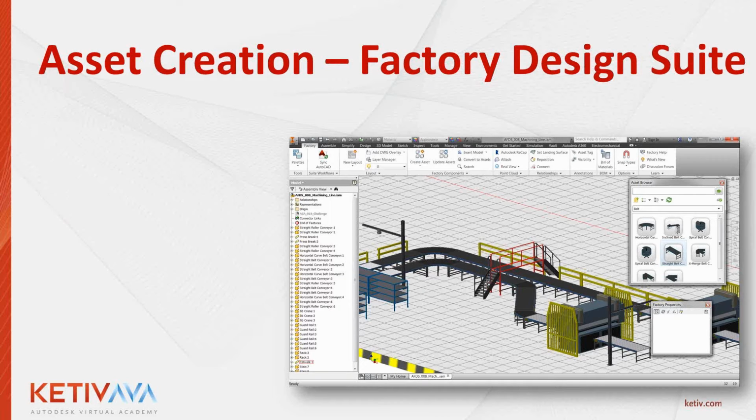So with that said, the goal of creating our assets is to make sure that we have reusable machines or assets. It doesn't even have to be machines necessarily. We've seen companies use this for office design. So it needs to be reusable. It needs to be easily placed. Typically when we create machinery, everything has to be very precisely placed, and so we use constraints, and in some cases it takes 2 or 3, maybe sometimes 4 constraints to perfectly place our nut or bolt or component onto another adjacent component.